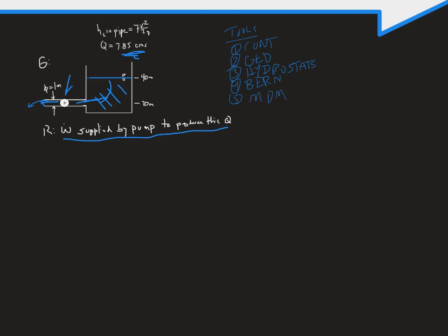Especially because this is the point of this lecture, we are going to eliminate Bernoulli and replace it with energy. There's no reason to use both. Bernoulli can be thought of as the inviscid version of energy, the part where there's no energy gain or loss. But we're now dealing with gain or loss because there's a pump in our control volume. So let's define our control volume. Here's our control volume, carefully chosen. Notice the pump is within the control volume, so we have to consider it.